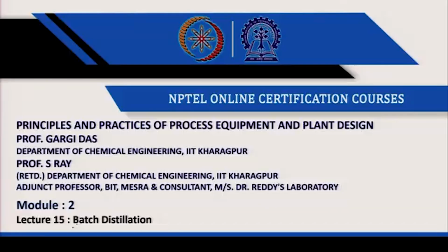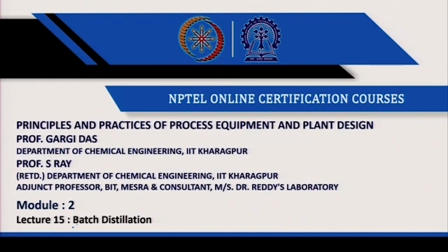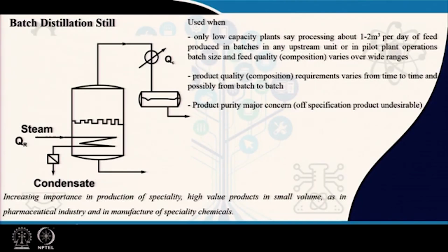So, hello everybody. After covering flash distillation, rectification or rather fractionation, today we are going to discuss batch distillation operations. Normally we feel that batch distillation is very simple and therefore it should be easy, but rather it is just the other way around, particularly because it is an unsteady state operation. So naturally most of the equations will be written in terms of differential terms, and that adds to the complexity of the design. But anyhow, batch distillation is not a very complex operation, I should say.